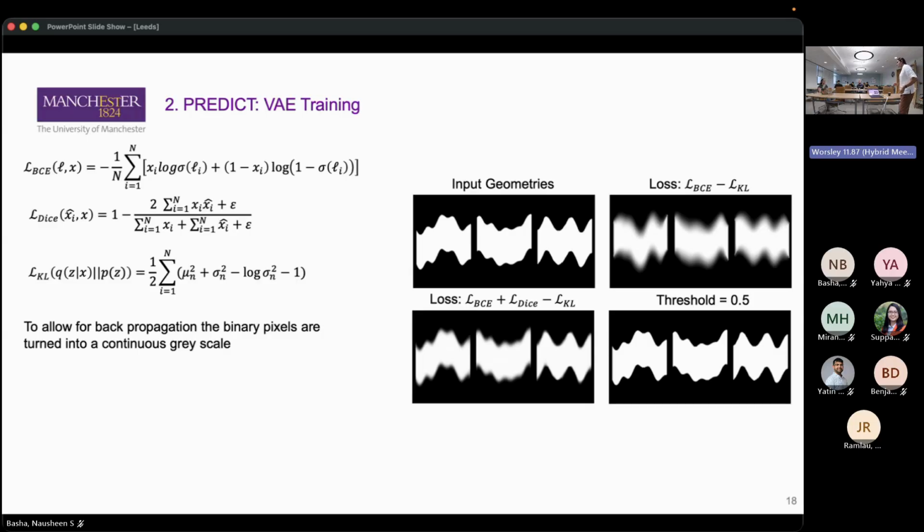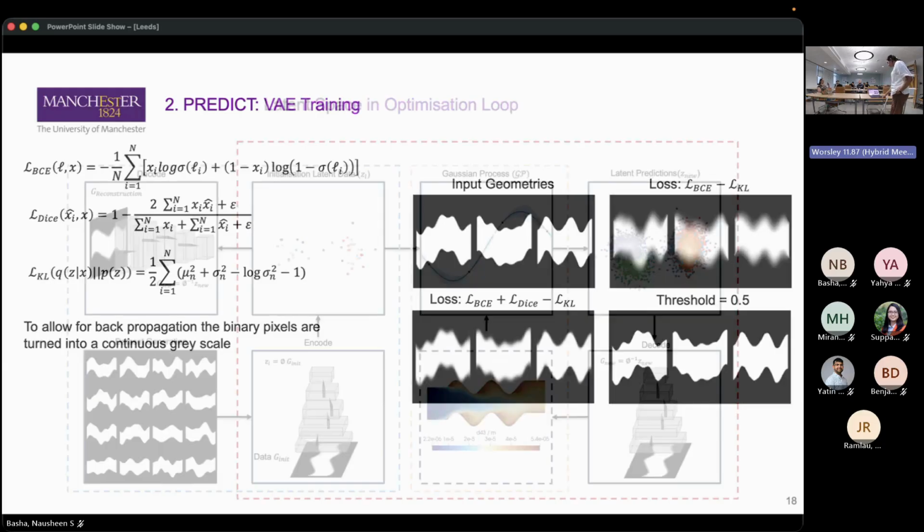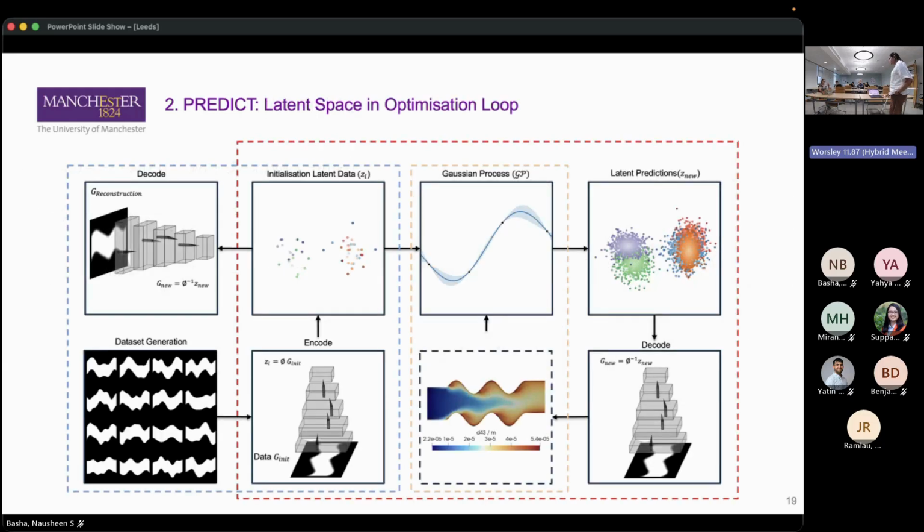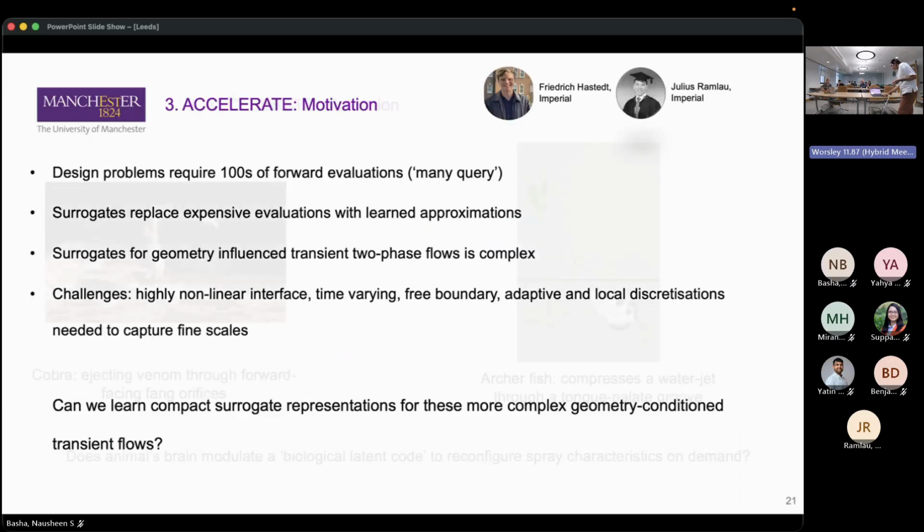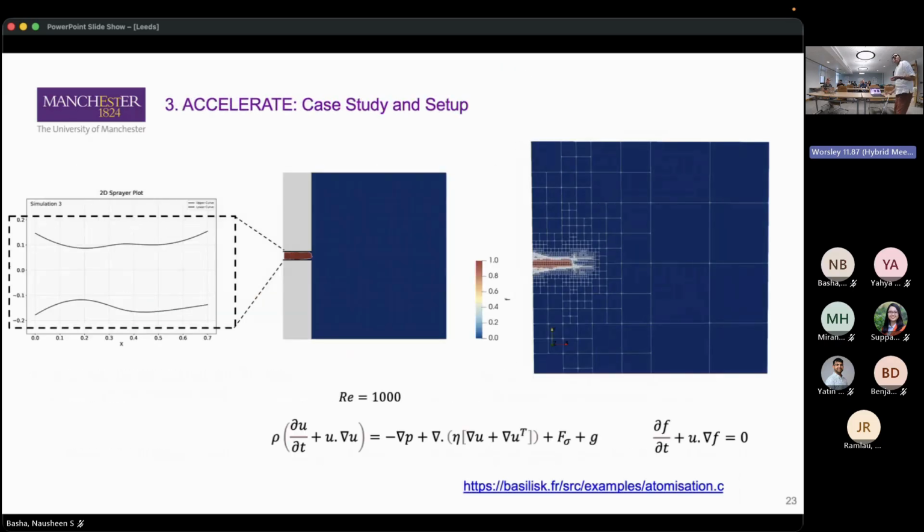And then a follow-up question, not for that, but for the mesh discretization, your adaptive mesh does those 4 subgrids. Did you look into other meshes, like triangular meshes, or is this just the? Okay, with this case of 2-phase flows, it's quite complex. So you could have triangular meshes, but the solver will suffer from quite a lot of numerical instability. So even with the adaptive mesh that you're looking for, right? So it is like on the order of 8.